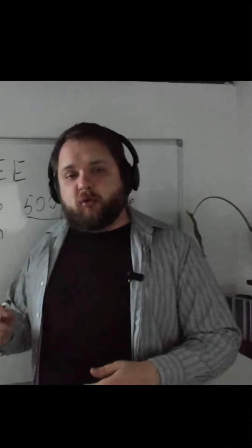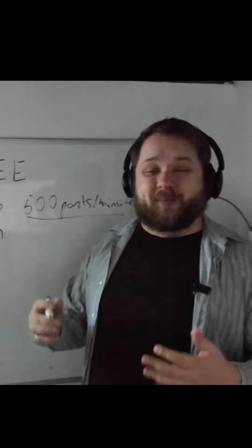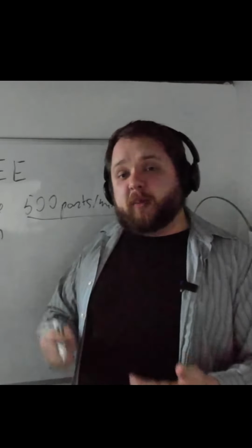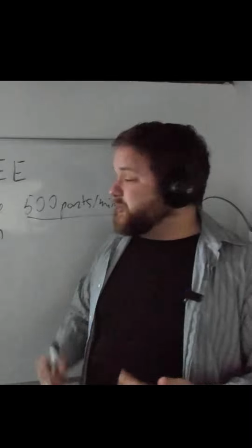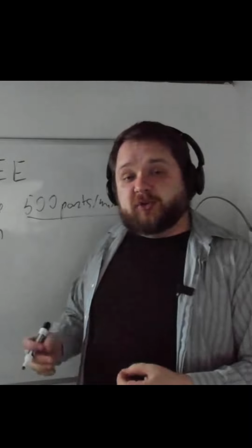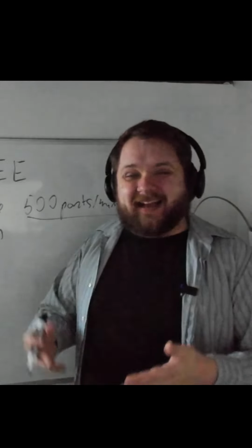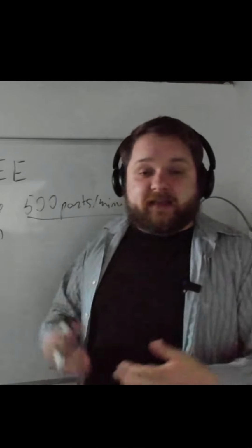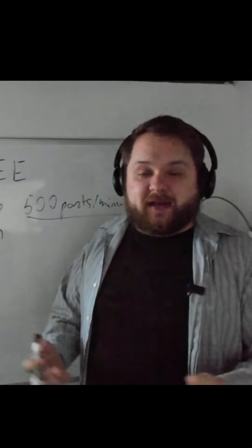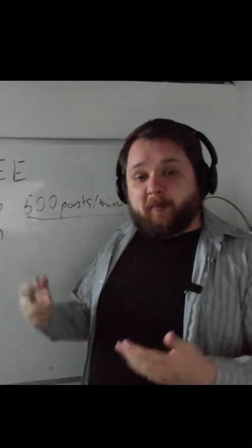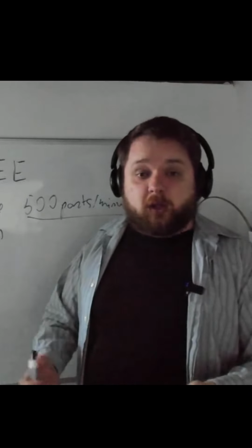The very common question or discussion point that you will get into based on what I've just explained is the fact that those 3 metrics can differ depending on the type of machine you're talking about. In some machines, you have 0 rejects, so quality is always at 100%. In some machines, you have a design for validating the quality of the product that's going through. It's essentially a conveyor belt with multiple vision systems. A vision system with just a conveyor is very unlikely to go down or be unavailable or have a low performance, but it is something that will reject parts all day, every day.